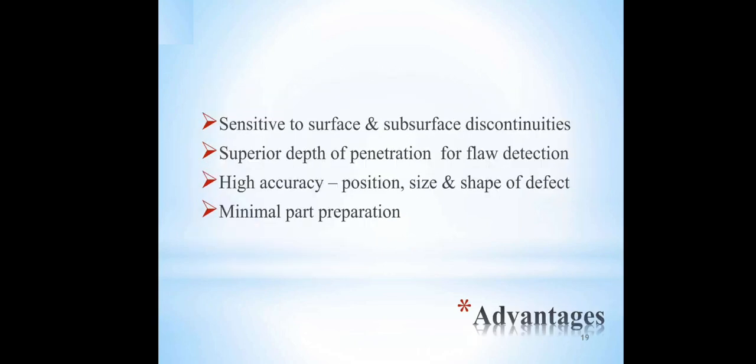Advantages of ultrasonic testing. Sensitive to surface and subsurface discontinuities. Superior depth of penetration for flaw detection. High accuracy in position, size and shape of defect. Minimal part preparation.